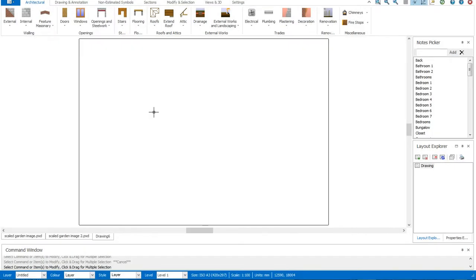This video is going to be a quick tip. Basically, if you are looking to do a set of drawings on an existing piece of land, either someone's back garden or a bit of waste that you're looking to develop, then this can help you if you have limited access to the site, so you can start laying out a set of drawings for proposals before measuring up. This method does rely on having at least one dimension that you can work to for your laying out, but you can also use the dimension tool on Google Maps as well, where we're going to source this image from.